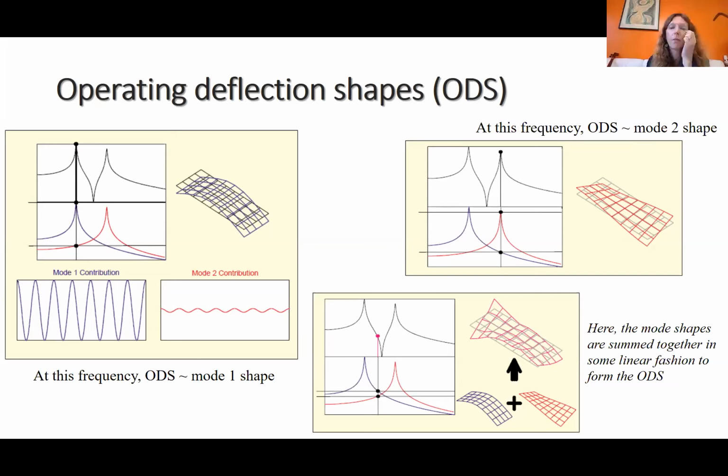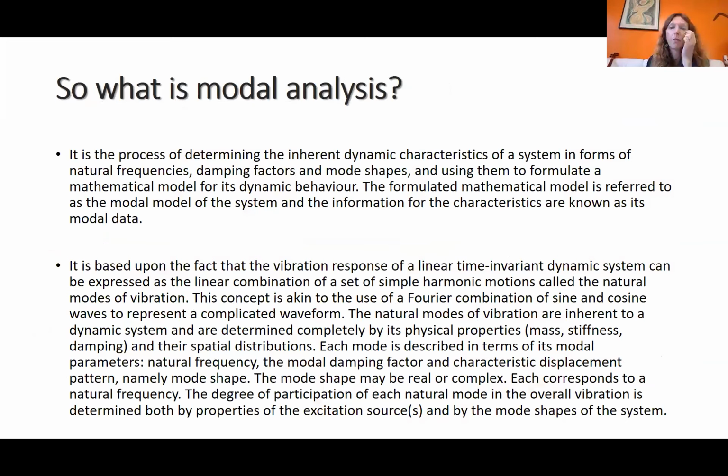So what is modal analysis? It's a lot of text, but if it's put online, you can go back to it and have time to read it, so you have something which stays with some explanation. It is the process of determining the inherent dynamic characteristics of a system in the form of natural frequencies, resonance frequencies, eigenfrequencies, damping factors, and mode shapes, and using them to formulate a mathematical model for its dynamic behavior.